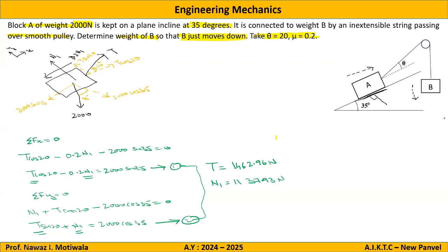Now let us draw the free body diagram for body B, because in the question it is asked for the weight of body B. I will also need to draw the free body diagram of body B. Considering body B here, there is no applied force directly, but there is a cable which is passing over a pulley towards A, and we have considered the tension in the cable as P. So I will show it here also, away from the body. Then self weight, which will be acting vertically downwards, which we are required to find out. Let us say I will assume that this weight is WB.